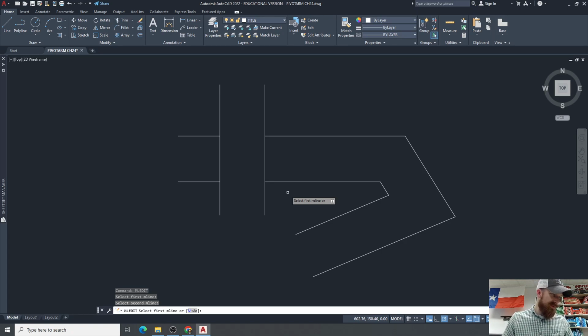And then the last one that we'll cover here, no, there's a few more. Overkill. Overkill automatically removes duplicate or overlapping lines, arcs, or polylines. In addition, if partially overlapping or contiguous lines, arcs, and polylines are selected, they will be combined to become one object. The overkill tool. I suggest you try that one out. Overkill, right? And then you can remove your duplicates, your overkilled stuff.